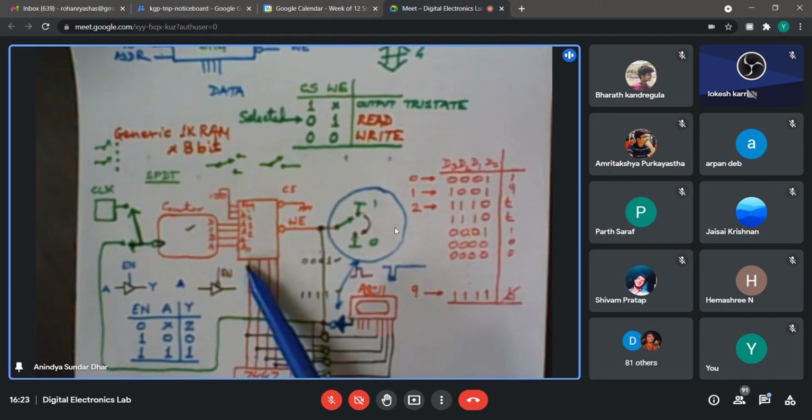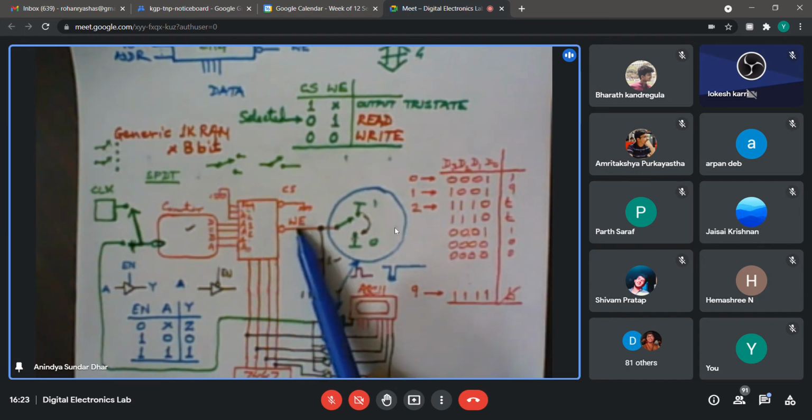Because the first thing is that it has to release the bus, it will be tri-stated. Otherwise, earlier it was being used as an input signal, and it's an output signal from this. Now I want it to be an input signal. Changing that one takes one tick, then writing takes another tick. So it is not happening in just a single tick period if I keep that write enable active only for such a short time. So I am widening that.